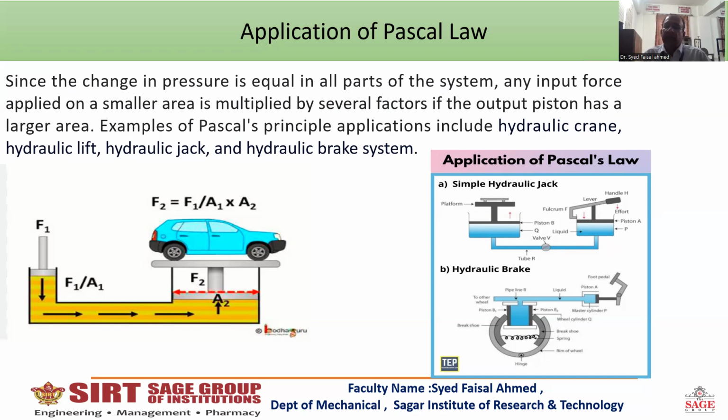Another example is the hydraulic brake, which in local language we usually call the power brake, right? The hydraulic brake works the same way here. There is a master cylinder, and when we push the pedal, this pushes the piston inside the enclosed liquid in a pipe, and the force is applied. Where the brake force is applied, there is a bigger, larger cylinder. Hence, the force will multiply, and the brakes are applied in this manner.